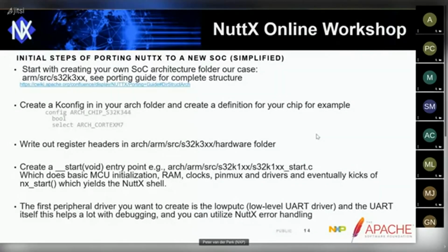And pretty much what you would have to do then is create a start entry point in your SoC folder, and think about the basic initialization you have to do for your microcontroller. So starting by clearing the RAM, setting up the clock, and creating a very basic pin mux driver.